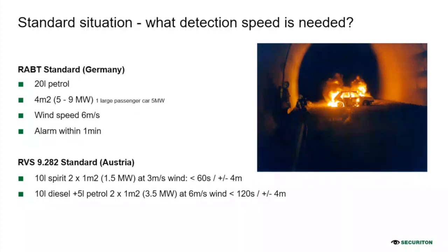80-90% of all heavy accidents where people die, it's because of the intoxication. So the smoke is enemy number one. That's why it's important to have all these tests to test the ventilation system together with the fire detection system.